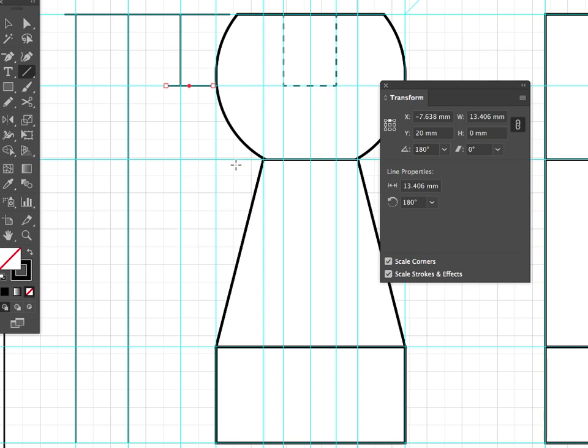Remember, projection lines don't touch the actual design. They're set apart by 1 millimeter. Projection lines also run over dimension lines by a few mil. We can now snip that long length of line, which really should be 3 lines, not 1. Use the scissors, which is under the eraser tool, and make sure you select the line first. That will isolate the line, and then you can snip it where it intercedes with the guide.